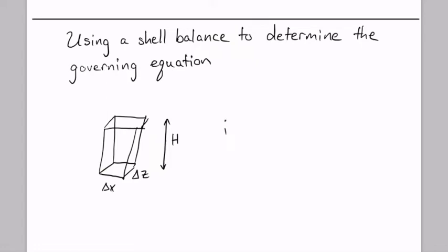So we have our usual energy balance, in minus out plus net generation equals accumulation. Here we're still at steady state, so the accumulation is going to be 0. And you're not told that there's any net generation, and you have no reason to suspect it, so we'll neglect that. So we only have to consider our in and out terms.